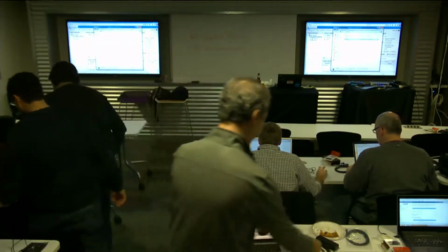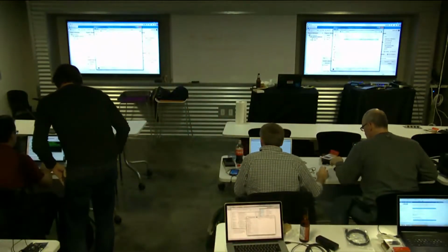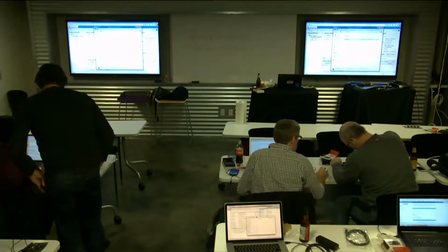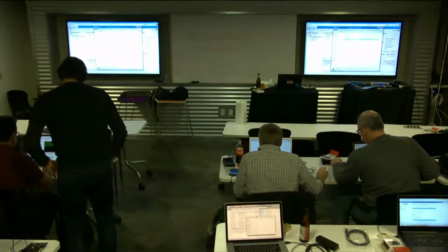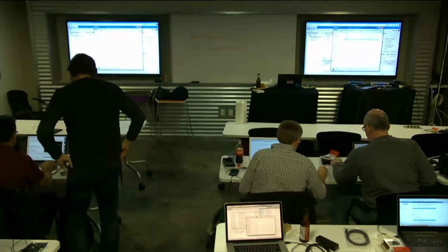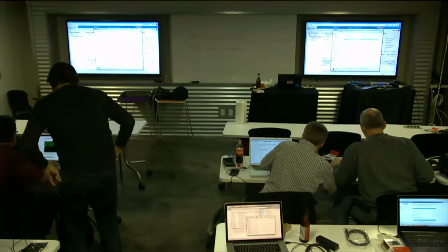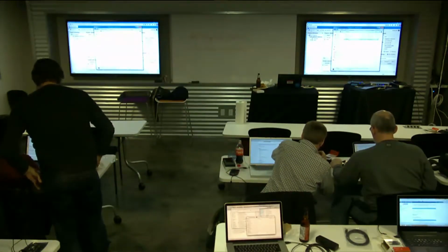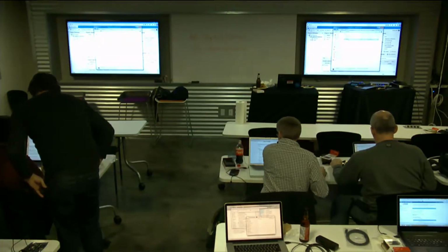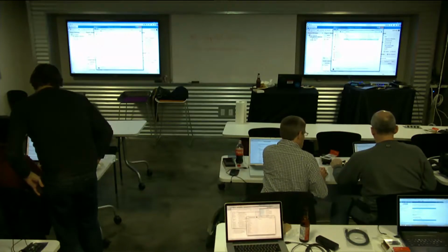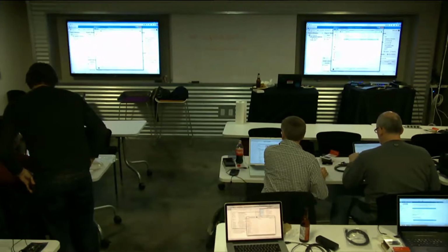Okay, so you unplug it. Hold down the reset button. Back in. I've done nothing yet. I'm just putting it into firmware mode. I need to put it in here. They're labeled LED 1, LED 2, and so on. Okay, so the drive should now mount as bootloader. It mounted as bootloader. The reset button can be really